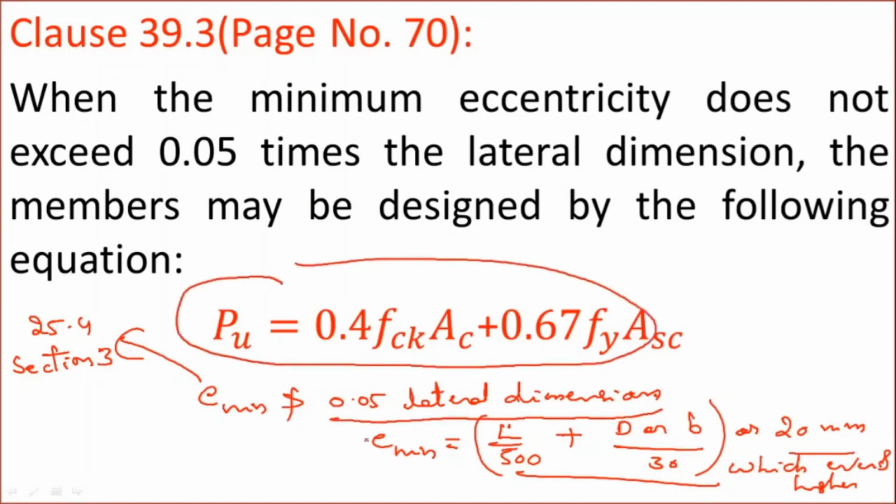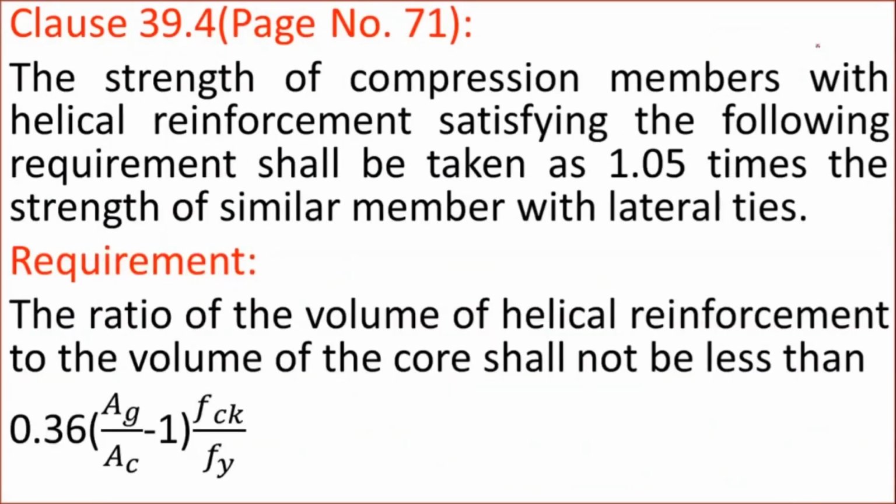Suppose the e minimum exceeds this condition, then the column has to be designed considering the bending. In that case it may be a column with uniaxial bending or a column with biaxial bending. In such cases you have to design the column using the SP16 charts.